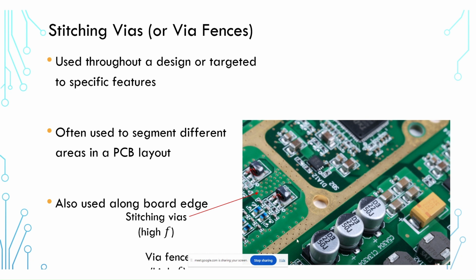Now, I think what you have to remember is that this is also being used to connect this exposed shielding to internal ground. That way you're basically creating a bunch of Faraday cages around these different portions of these circuits. And again, that's meant to provide some shielding between, for example, an RF section, a digital section, a low frequency analog section, and possibly even a power section.